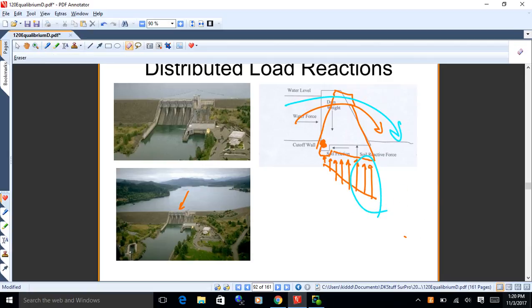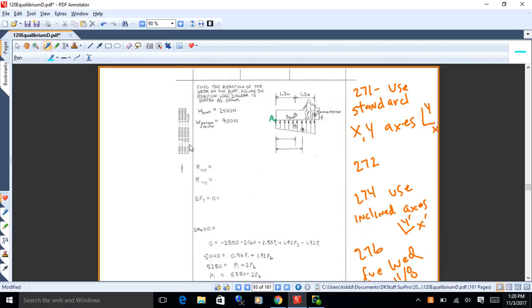which is probably about the biggest unknown I know in engineering, soil strength. I mean, they write it up, and they always give you a nice report that says how strong it is and all that, but then they always qualify it. Well, we don't really know. It might be this, it might be that, because soil is pretty weird stuff. I mean, you can drill here, get one thing, drill 10 feet over and get something else. So that's what safety factors are for. Yeah, there are big safety factors on soil.